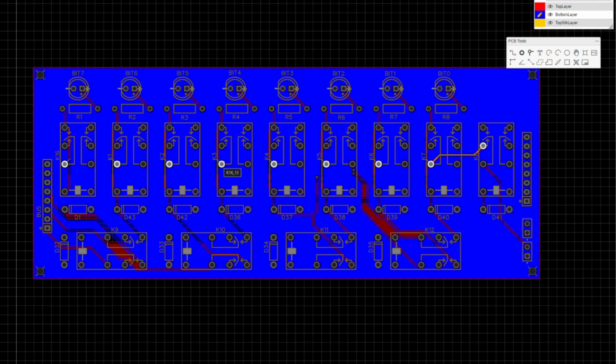And if you see, all of these pins are linked together and they come to this relay, which is the reset relay. If you put power into this one, it goes from normally closed to normally open, and the power won't come through here anymore. So it's basically an inverter. Cuts the power off, and that cuts the power to all these. So if there's a bit held in any of these, it will reset it.